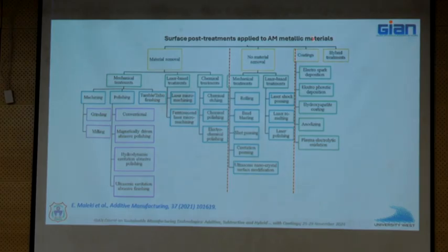Yeah, there are other methods also that you should be aware of, where you can dramatically change the surface attributes, but you don't remove material. What could those be? It could be just bead blasting, where you can use almost like shot peening, or grit blasting with softer beads, where you don't remove material.